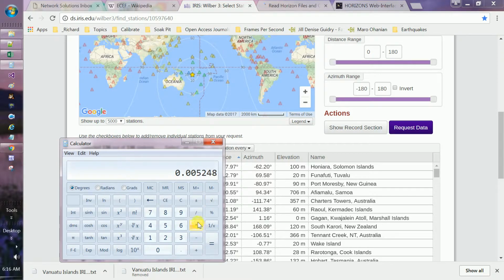I multiply it by my sample rate, say 1 megahertz, and I have to shift by 5248 samples to do the correlation, or at least to start looking. So that's my strategy in here, how to go in and use that.